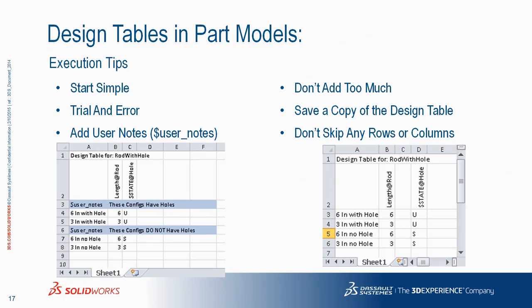Also, as you're putting in all these different items, save a copy of the design table. We can easily highlight this, start up a new Excel window, and paste it into there. The last thing you want to do is go in and make 100 different changes to your design table, have one syntax error in there, go to click outside of the design table and it says, oh, I'm not going to update it, and you lose all your changes at that point in time. Nothing worse than wasting all that time.